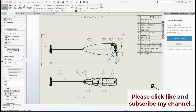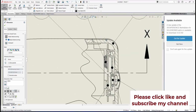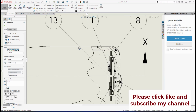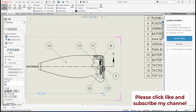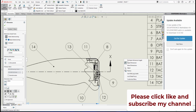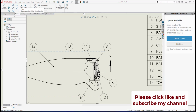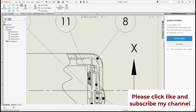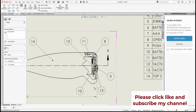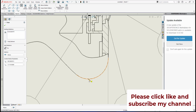Another thing, maybe I can show the width of this frother, but sometimes I cannot put it, since I have done a broken out section and also modeled this by lofting. If I cannot snap the dimension to any point, I have to go to Sketch and add a point. I locate a point here, snap at this end point, and add another point snapped at this edge.